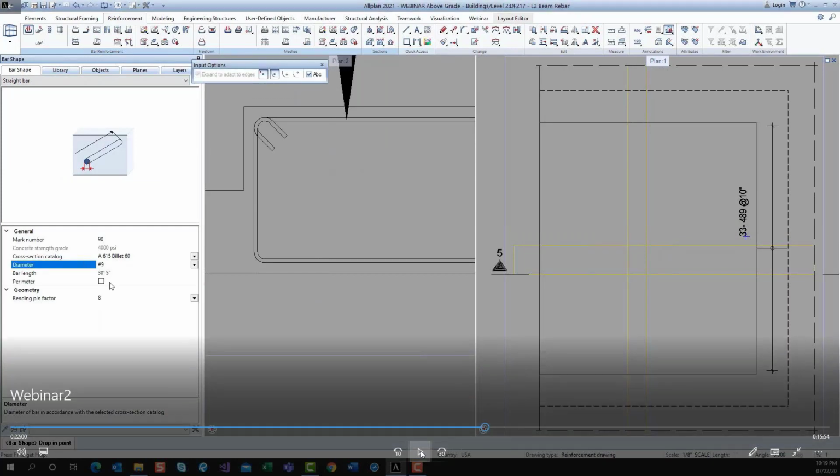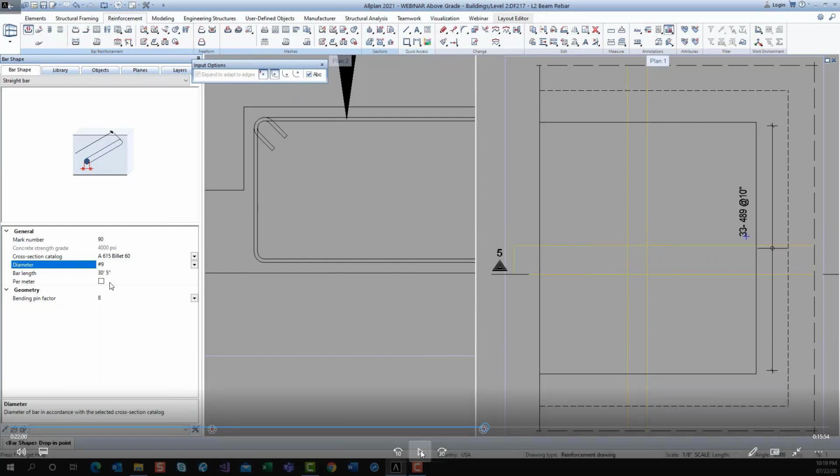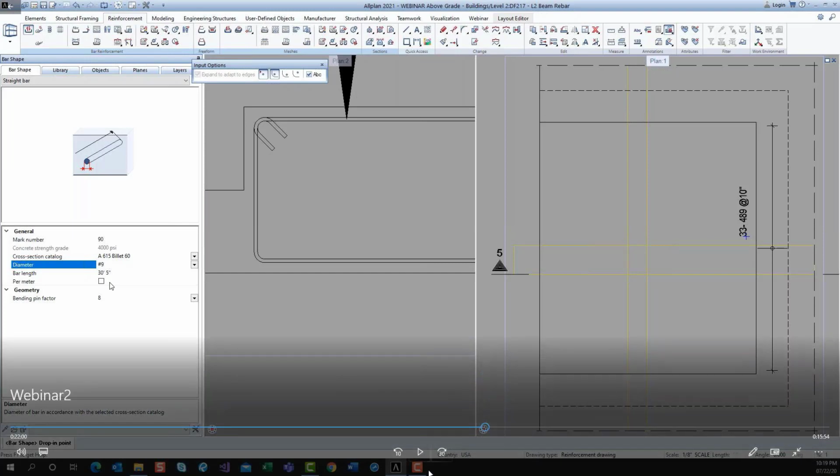So one of the things I'm going to show you here is now I'm going to place the verticals. In this next portion here, notice that I'm placing the bar as what we call our section view, our dot view. But I'm also going to use our length tool, our measure tool, to copy and paste information into. So if I don't know how long a particular segment of concrete is, I can use the measure tool and I can then inherit that information anywhere I want and use that. And then you'll also see me using some arithmetic equations to get the proper length of the bar. So when I put it in section mode, it needs to know the length of the bar I actually want to create. Well, I don't know that off the top of my head, but I do have concrete. So I'm going to show you how we use that.